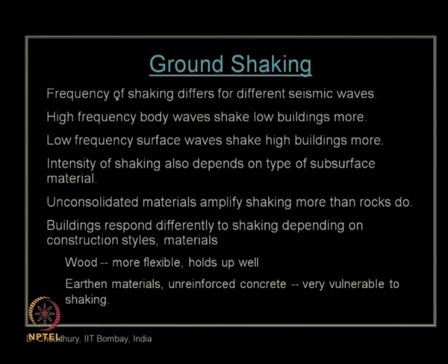That frequency of shaking differs for different seismic waves, and typically it has been found that high frequency body waves, which are waves that go through a body or media, in the sense soil or rock media much below the ground surface, not close to the free surface, like the primary wave and secondary wave, shake the low buildings more, that is low rise or shorter buildings like single story or one story buildings.